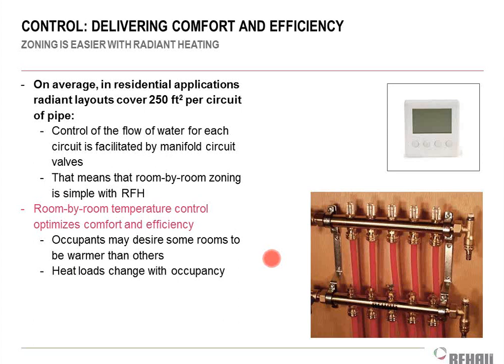Residentially, we like to keep the tube spacing pretty close because people like to walk around barefoot. Oddly enough, one of the selling features for having a radiant heated floor in your house is you can walk around barefoot in the winter. So that's kind of what people want, so we do it that way. It tends to dictate that we put the tube in closer, which means smaller diameter pipes, which means not quite as much distance on the circuit. The larger commercial ones, we spread it out a little bit more because you typically have a layer of carpeting, and then you've got shoes on and stuff like that.